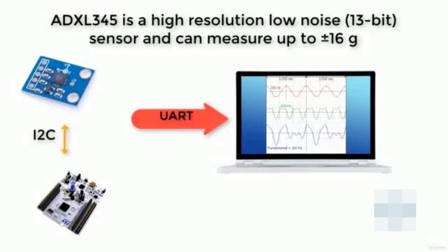We will interface the ADXL345 accelerometer sensor to our STM32 board and will capture the X, Y, Z axis data via the serial port of the STM32 on our computer in raw form. In our case, we need to capture the vibrational pattern. We are more interested in the linear acceleration produced during the vibration than the gravity. To exclude the gravity, we will use a low-pass filter in our code before feeding the data to the model.